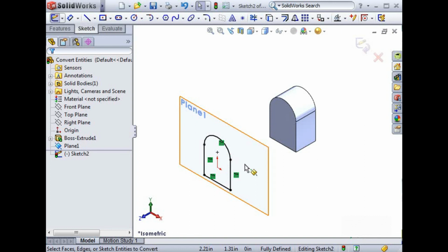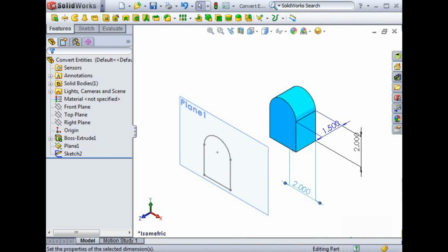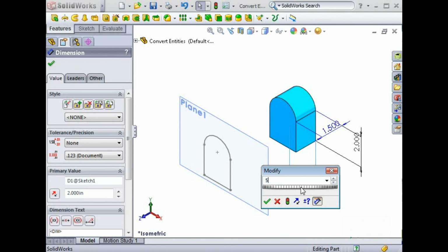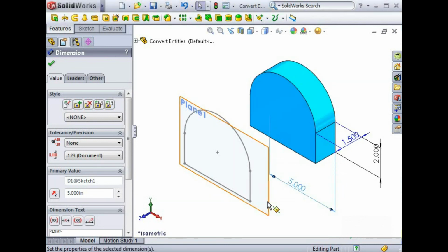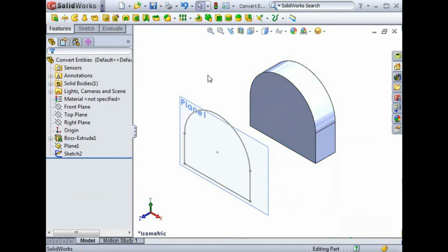As I mentioned, the on-edge relationship is special because it will change to always mimic the geometry that it's based on. So if I change the shape of this tombstone, notice that the sketch changes and updates as well. This is a very powerful parametric capability of Solidworks that we will expand on in much greater detail later in this course.